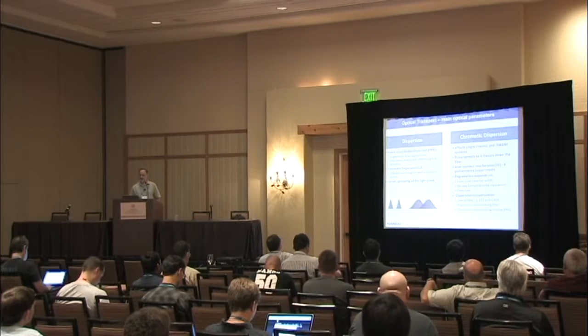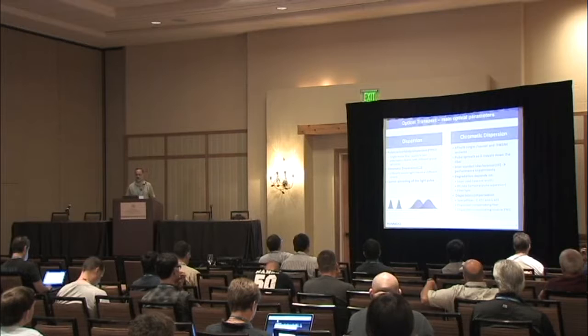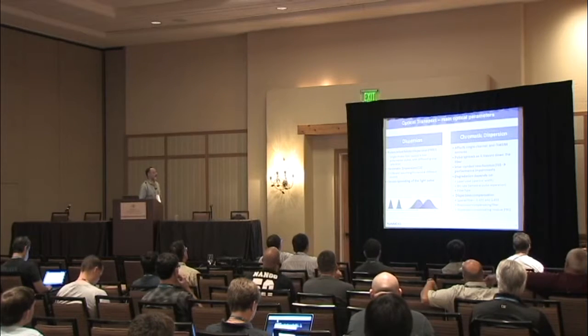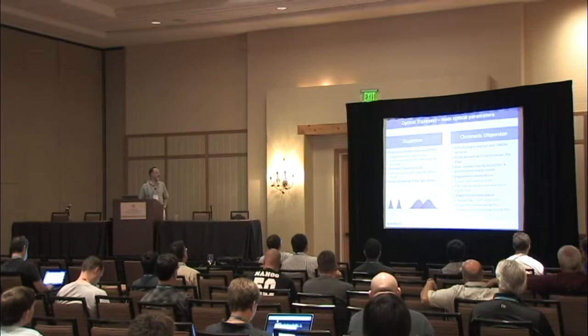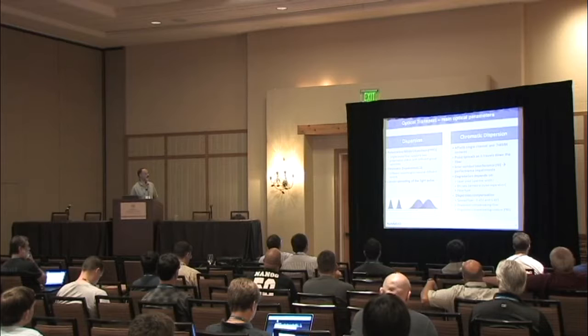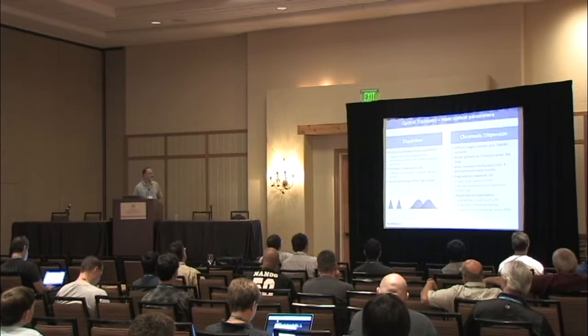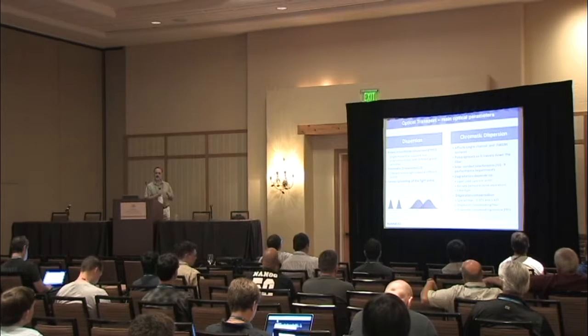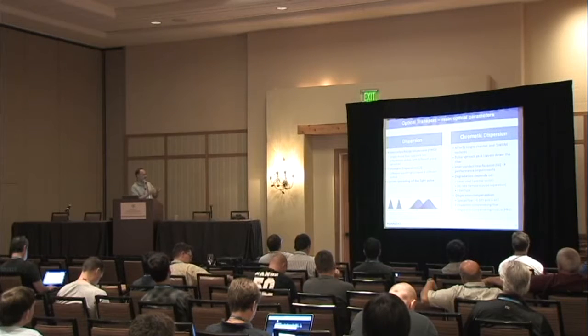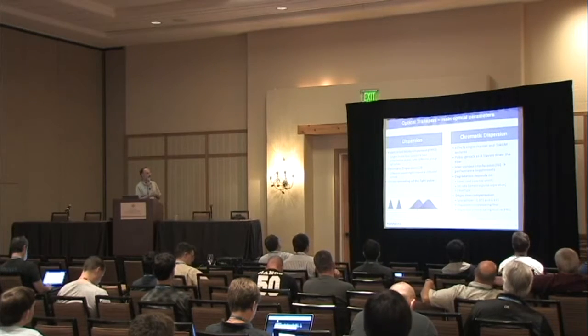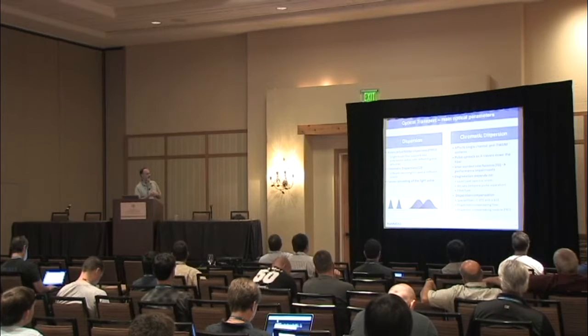So let's talk a little bit about dispersion, caused by two phenomena in fiber. One is polarization mode dispersion, and that's caused by the two polarization states of the fiber that have different speeds, different velocities. Then you have the chromatic dispersion, when the different wavelengths travel through the fiber at different speeds. Both phenomena of variance in speeds cause basically spreading of the light pulse. And you see the picture, this spread of the light pulse.